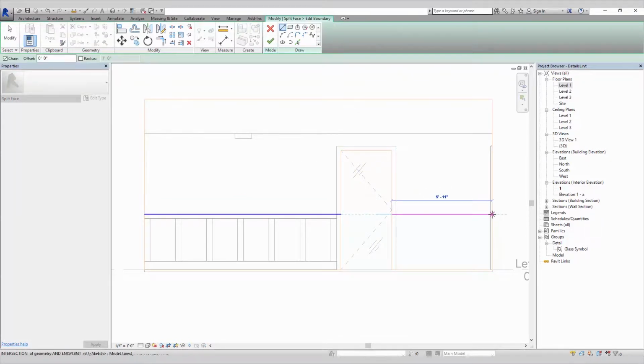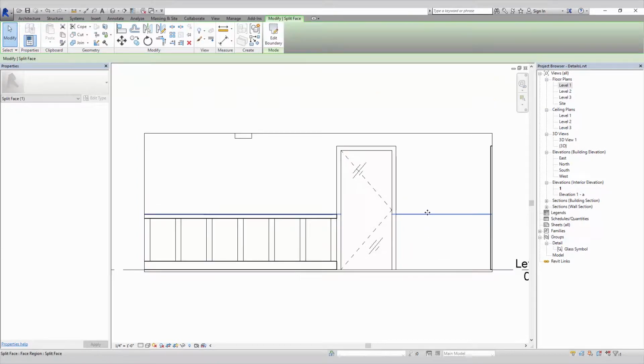So if I want that material to be changed above these purple lines, then I only need to draw them connecting to the orange outlines of the wall. And you can see that now divides our wall from top to bottom. I could copy this pattern over there later on. But let's now add a different pattern to the top portion of our wall.